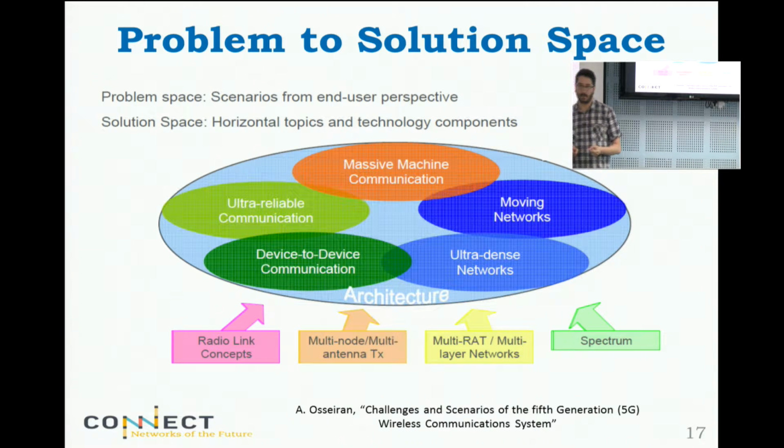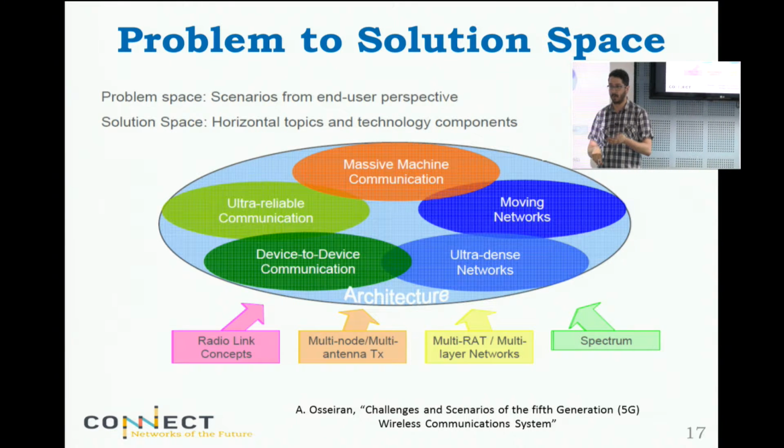Now, one smart thing they are realizing now in the physical layer MIMO is that in the past, they simplified the problem, and they said you can have many antennas everywhere. The truth is, it's very difficult to accommodate many antennas in a small device for a few reasons. Complexity. Every antenna needs a dedicated RF chain, and the more antennas you have, the more complicated is your signal processing, which is bad also for power consumption, right? So it's not good for a handheld device, for example.